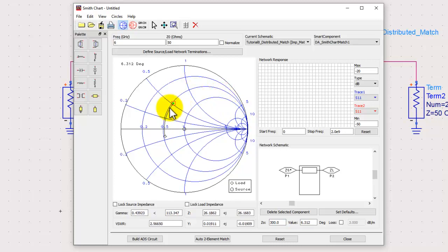But that's what the theory is, because now with higher impedance you will have a very thin line, and when you have a very thin line your capacitance will become almost negligible, so this line will start behaving like a pure inductor.